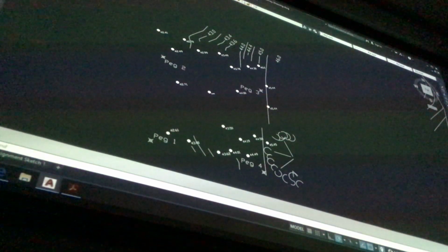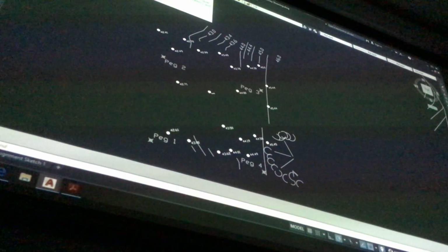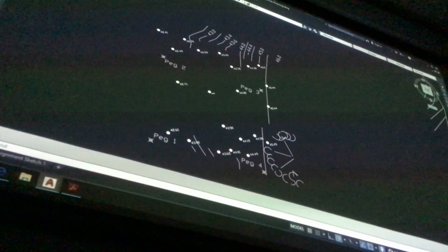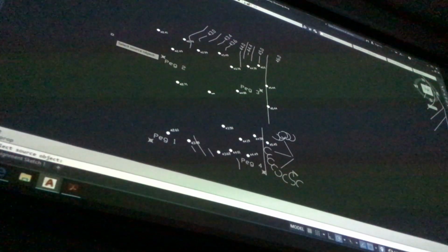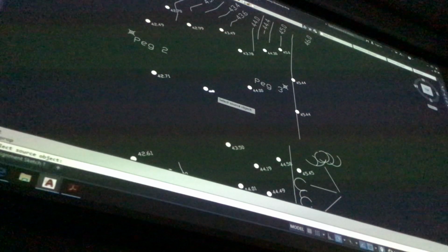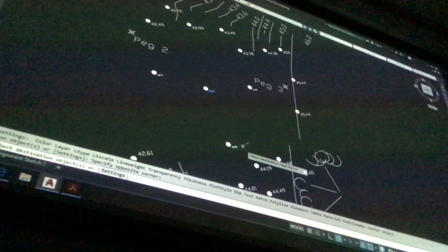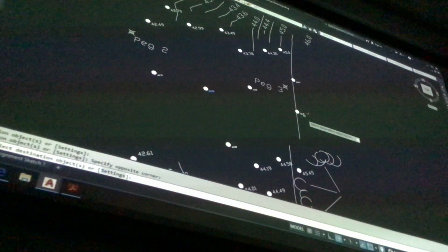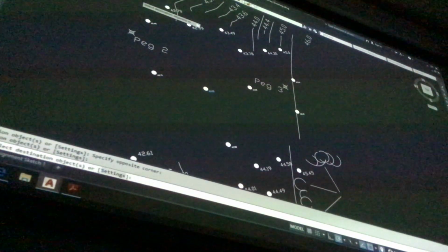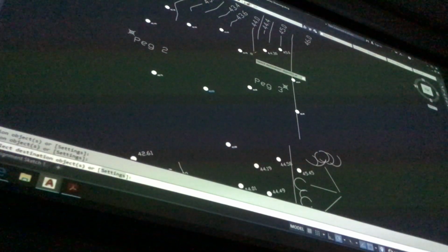So I go up here to this thing here called Match Properties. I click on it. I call it the paintbrush because when you dip the paintbrush in what you want, which is that one, I can now basically go around them all, and within seconds, everything it touches will go to that same text height.